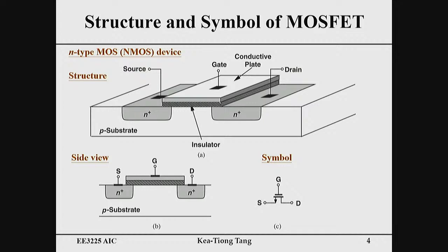And if the carriers are electrons, the electrons will go from source to drain, resulting in a current from drain to the source. So basically, if we switch the bias voltage between drain and source, then the direction of the current flow will be the opposite. Okay, so you have to pay attention how you bias the transistor.